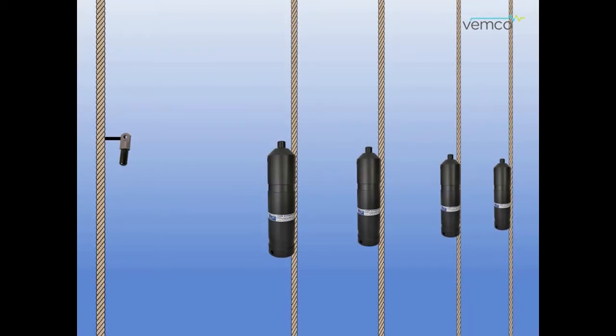A range test is a test, or a number of tests together, performed to determine a receiver's ability to decode transmitters at various distances and in varying conditions at your chosen research site. This can be done in a number of ways, but a simple method is to use a range test tag with a fixed time delay at a fixed location, and a number of receivers at fixed locations that are known distances from the tag.